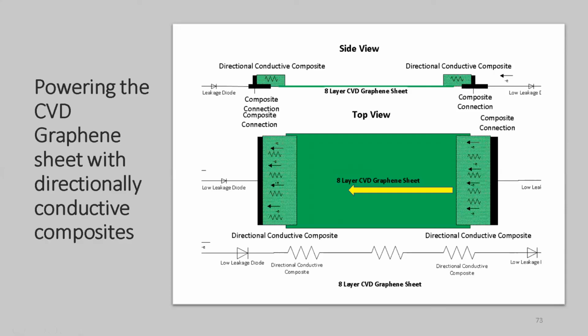You put them into an epoxy substrate that's high dielectric, and you keep adding them, just like you would when trying to make a dielectric for a capacitor, until you cross the percolation limit, and quickly the resistance of the material drops to a low value, and you can tweak the value to what you want.